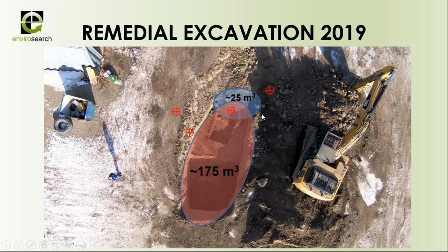So if you look at the data from the initial assessment, this borehole was the one where we'd found the contamination, but it actually wasn't the location where we had the highest concentrations. It was kind of on the edge of the plume. The plume had snuck in between, just east of this point here, and it extended quite a bit further than had initially been estimated.